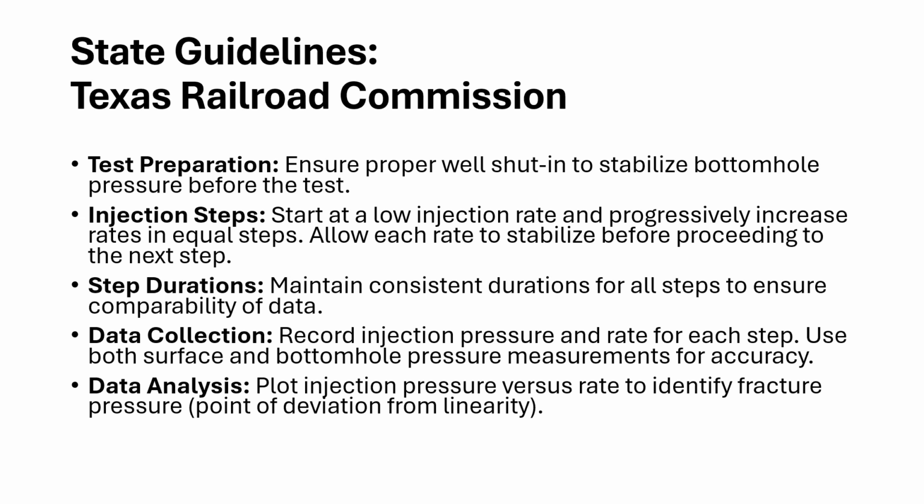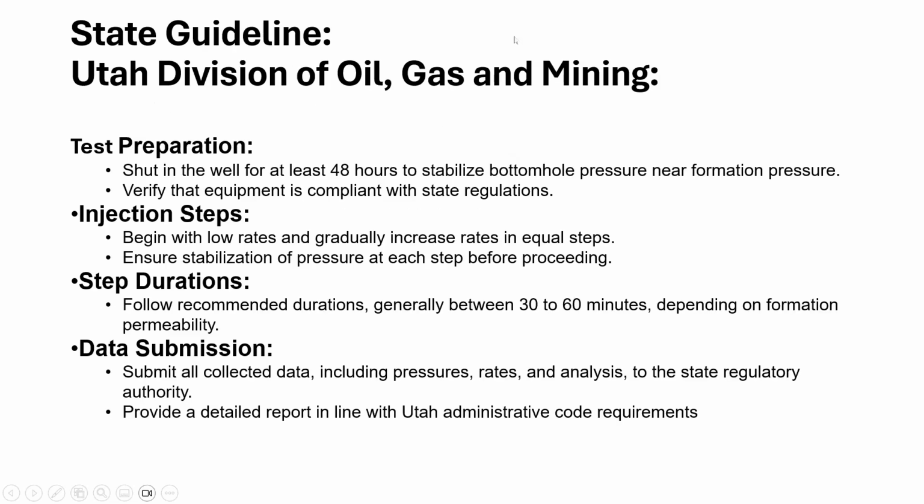They recommend the use of both surface and bottom hole measurements. And they recommend, again, that you plot the injection rate versus time. Utah has published theirs. They recommend a 48-hour shut-in. Again, begin with low rates and gradually increase in equal steps.